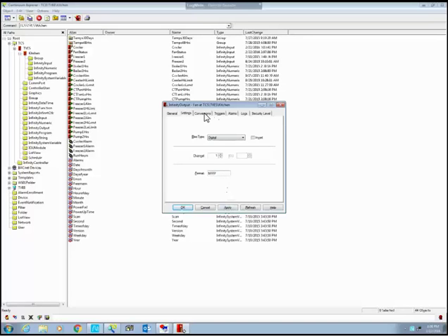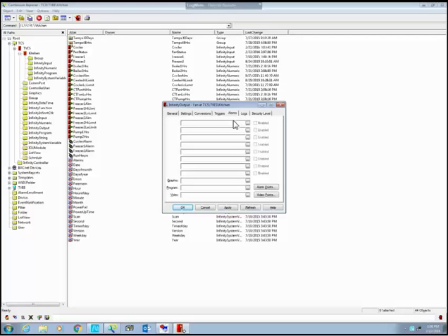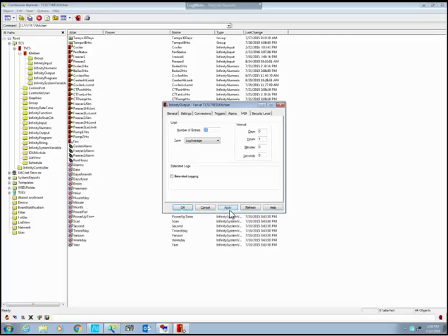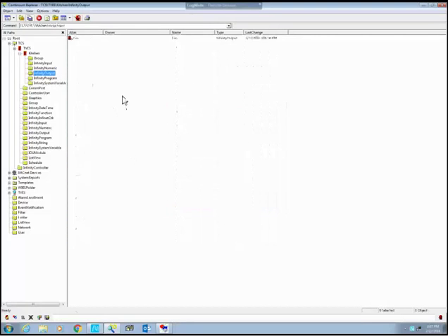Okay. There are no conversions. There are no triggers. There are no alarms. If we want the same log as the other one, we'll put 24 hours average at 1 hour apiece. And we'll apply. Now you'll see that this tab came up under the kitchen controller. If you go there it is. It's going to come up.